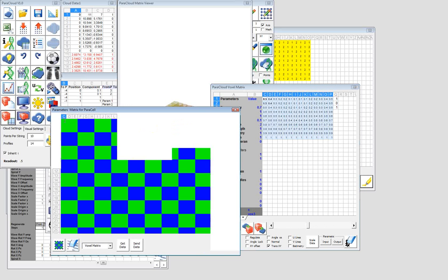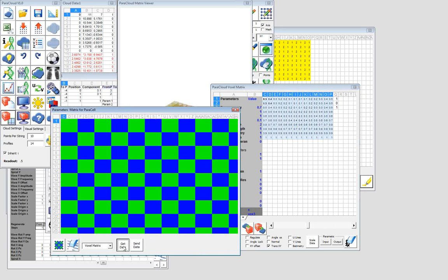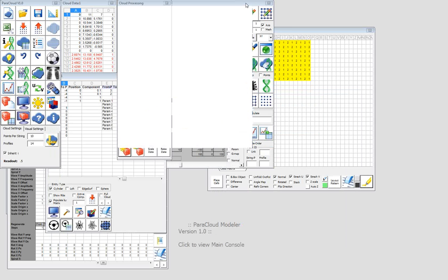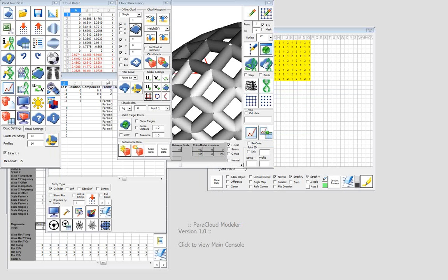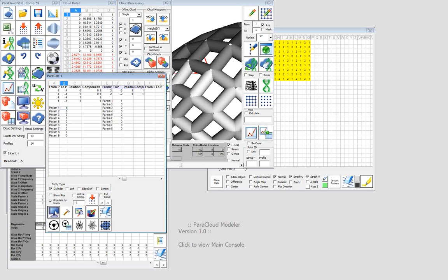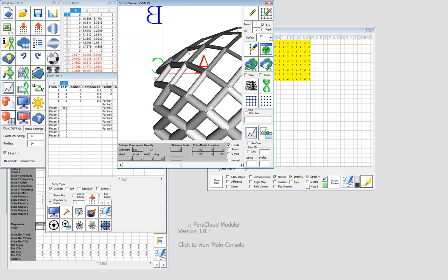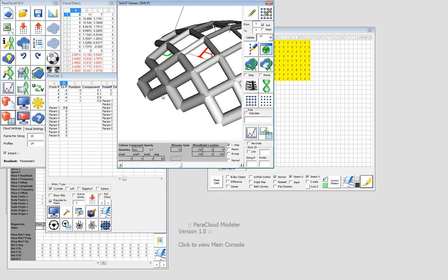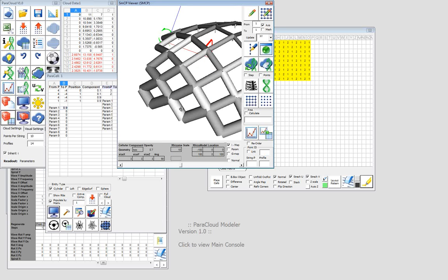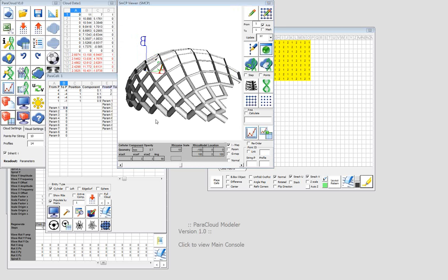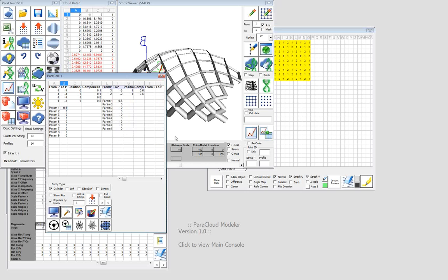Now by selecting the value for parameter 1, I could simply get the data in, and this is aligned properly for the process of applying it to my design. So I'm going to preview that. It's going to read the value and write those here to the viewer so you can see how it drives the size of the component. And when we're happy with the result, we can simply build it here and replace this piece of geometry. We can press the build button, go to Rhino, and you can see that it builds the geometry in Rhino.